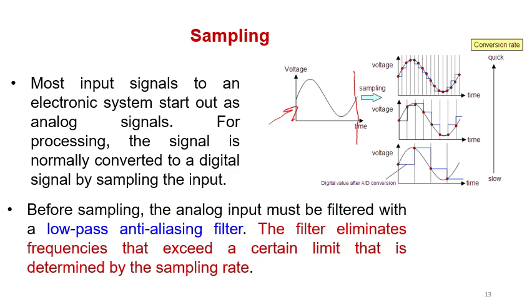If you notice here, we are taking certain samples, such that here I'm taking a value, here I'm taking a value, here I'm taking a value, here I'm taking a value. If you look at the representation of the sine wave, it has this shape. Now, if I improve it a little bit, let us increase the sampling frequency. Increasing the sampling frequency means increasing the number of discrete values used to represent the analog signal.